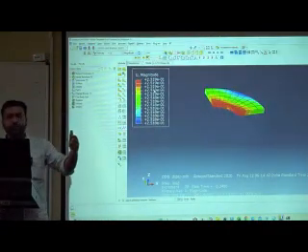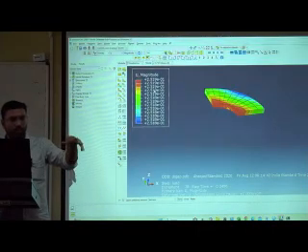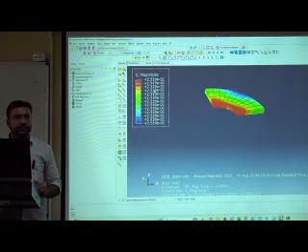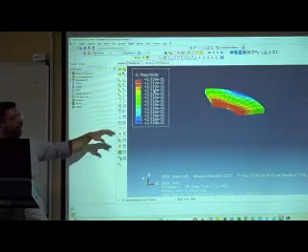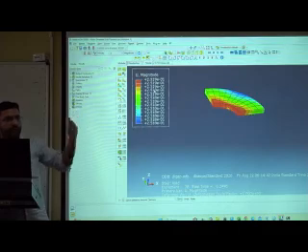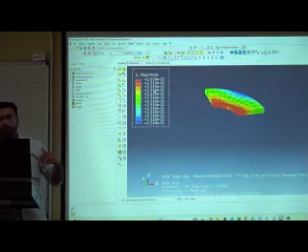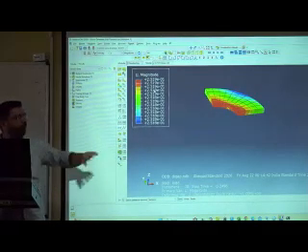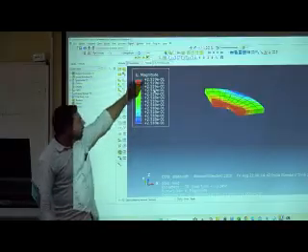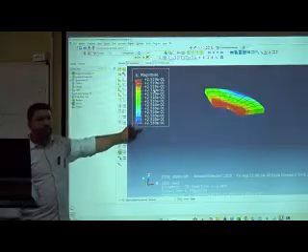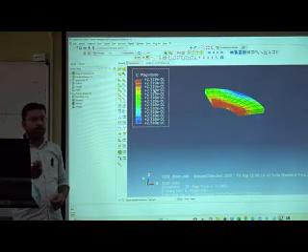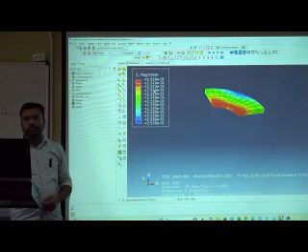But if you go for the pressure, you will see a major 1 mm, 2 mm difference is there. So we have observed that the inner part settles more than the outer part of this ring foundation under the uniform load. Okay, so this is the important thing. Okay, all the values are nearly the same. 0.001 mm is the only difference.